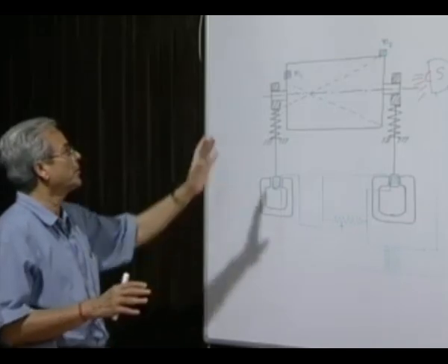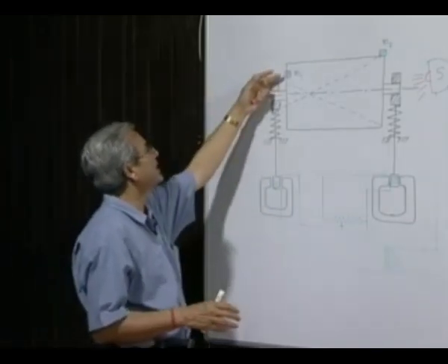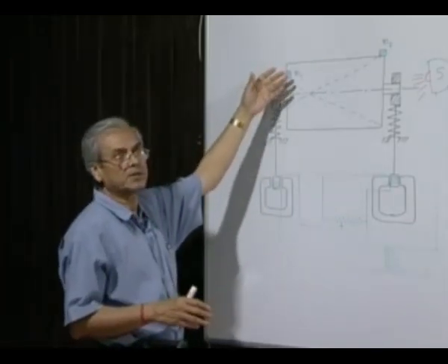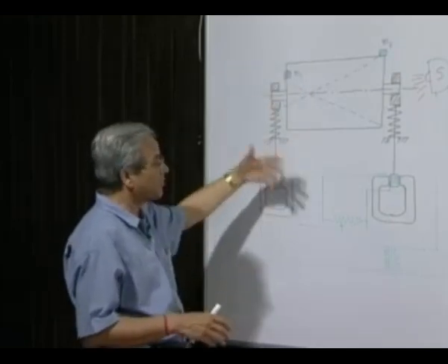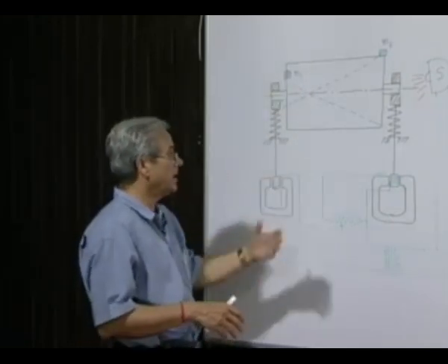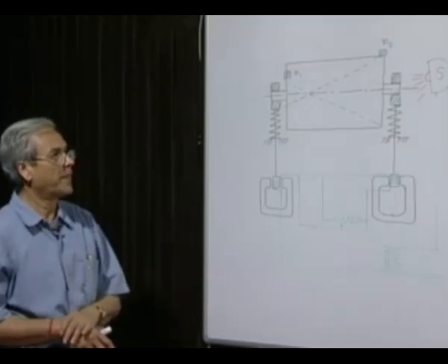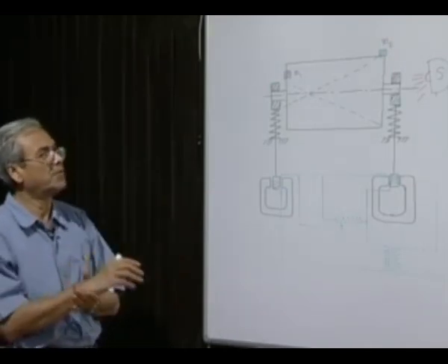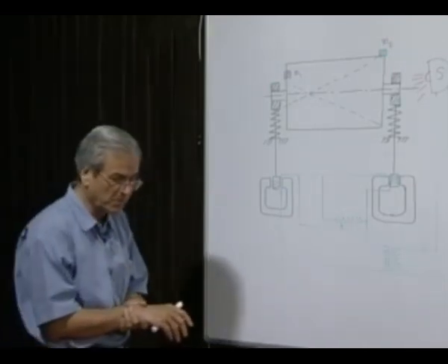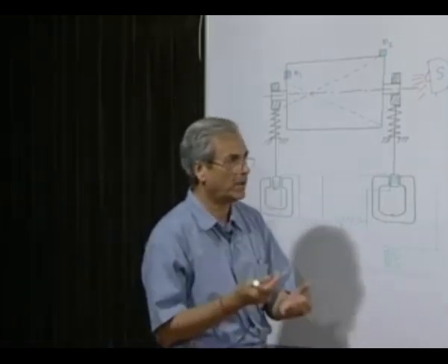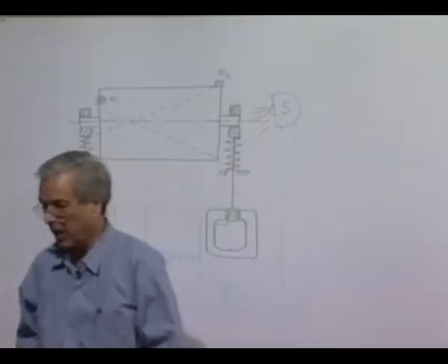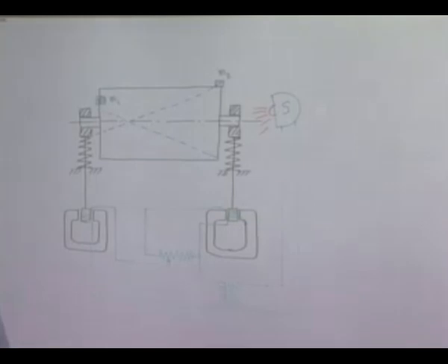The basic principle is that you slowly adjust the magnitude of the mass, or the product of the mass and its eccentricity, in such a way that the result is minimized to 0. So, these are the principles of balancing machines, which are used for balancing actual rotors when they are not very large.